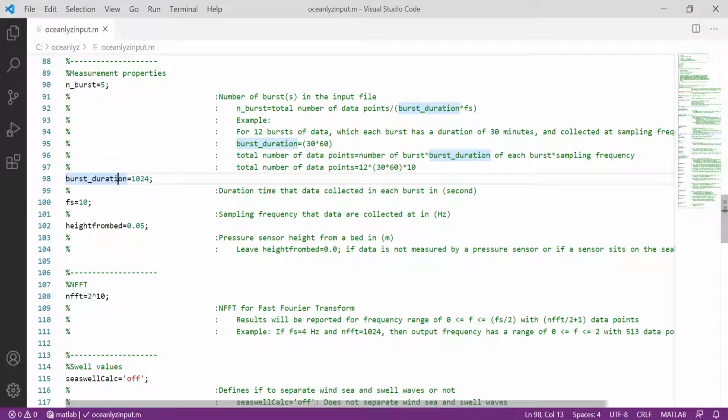At the beginning of every hour, our sensors measured data for 24 seconds, and after that they go to sleep. At the start of the next hour they wake up and measure for 24 seconds, then go back to sleep. At the start of the third hour they wake up and measure for 24 seconds, and this is done for 5 hours. So we have 5 hours of data, but it is not continuously measured. We have only 24 seconds of data in every hour.